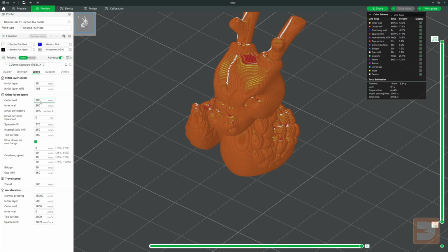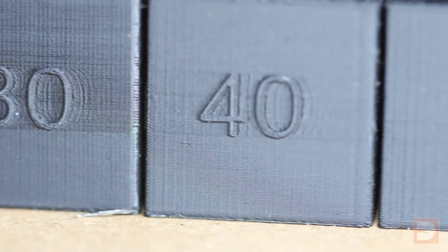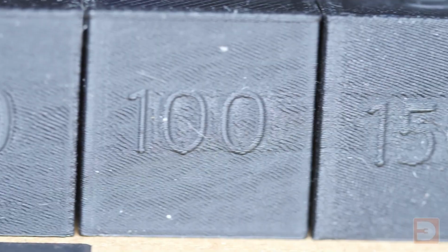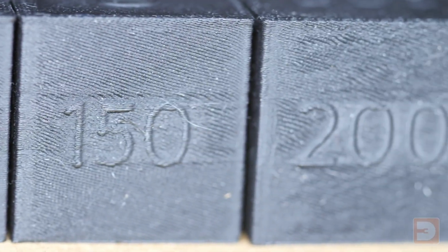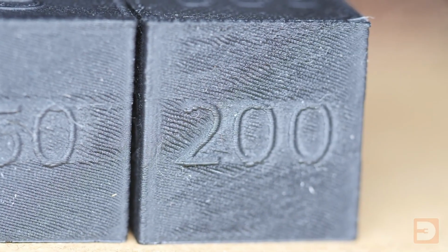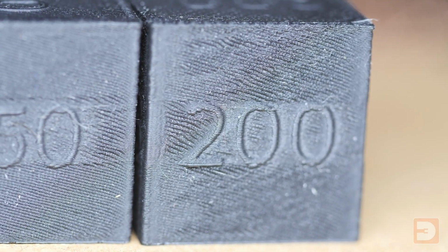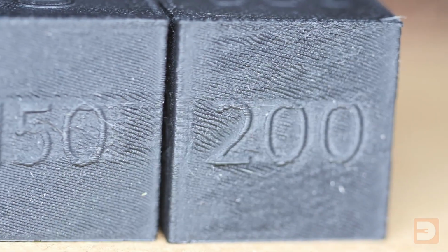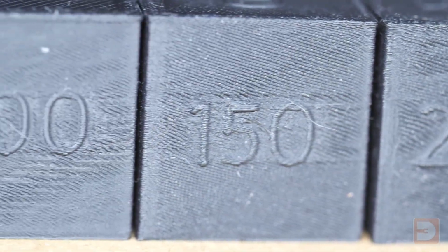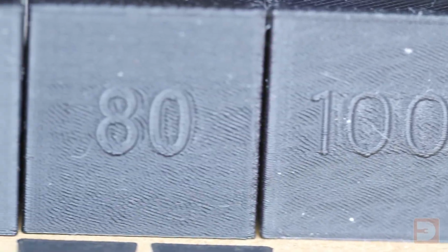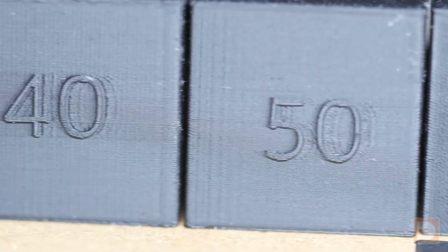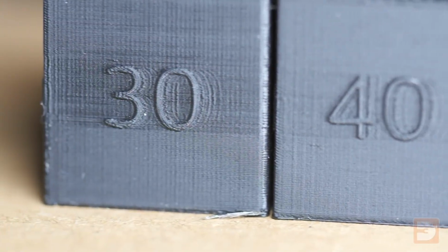It's also worth noting that whilst printers like those by Bambu can print exceptionally fast compared to the 40 to 60mm a second of the old standard, even if the material you're using is capable of printing at these speeds, it can affect the surface texture, with people often surprised by the normally shiny prints now looking rough or matte. If you're having that issue, try slowing down just the outer wall speed, as that is the section of the print you're going to see and won't significantly impact the overall speed of your print. I often have my outer wall set to more like 40mm a second, even if I have other speeds at 200 to 400mm a second.